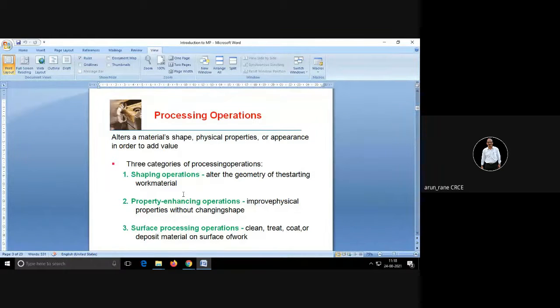Okay, so shaping here is slightly vague. If it is gear shaping or a shaping machine in the machine shop, then it is a chip removal process. But sometimes shaping operations like casting or forging are also called shaping operations because they give the shape to the product. So in that case, it is chipless.